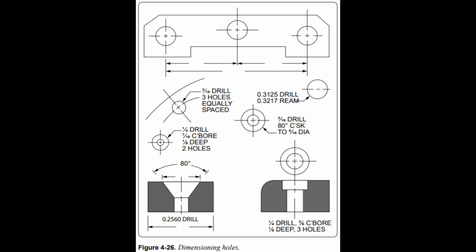Sectioning lines. Sectioning lines indicate the exposed surfaces of an object in a sectional view. They are generally thin full lines, but may vary with the kind of material shown in section. Phantom lines. Phantom lines indicate the alternate position of parts of the object or the relative position of a missing part. They are composed of one long and two short evenly spaced dashes.